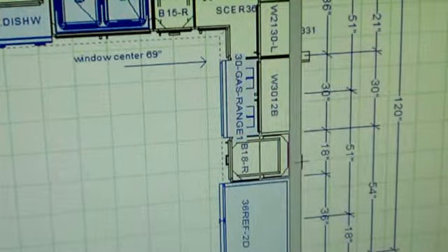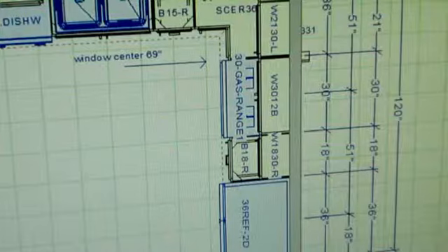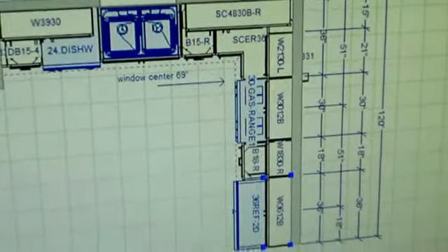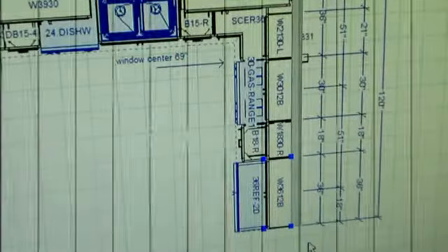I'm going to be using 12-inch high above my appliances. That's what I prefer to use when it comes to a space saver microwave. And I also prefer to use a 12-inch above a refrigerator because you can always go bigger in height and never have to worry about it. Plus, as you'll look at the finished plan, it's very symmetrical.